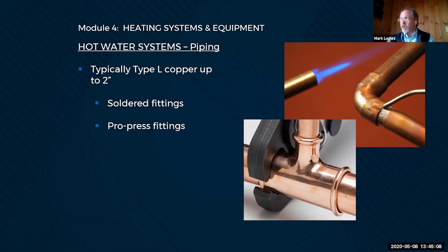I said, well, we don't do too much brazing unless we're talking about refrigeration systems or medical gas systems. But he did make a good point. A really good plumber or a good heating piping guy, when he's got to run copper inside a wall, will take the extra time and effort to braze it because that's a joint that's never going to go. You can lose a solder joint, you can lose a ProPress joint. It's rare, but it happens. Brazed joints will be there long after we're gone, unless somebody tears the building down.